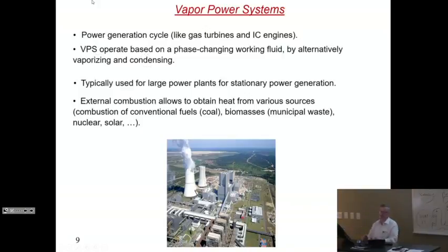That is quite important, because if you look at your thermodynamic tables, at your steam tables, going from a liquid to a vapor implies a very high change in entropy, in enthalpy or in internal energy, much more so than heating up a gas or heating up a fluid. Going from fluid to gas takes a lot of energy. So it takes a lot of energy and it gives a lot of energy, which means that these things are actually quite compact. They have a lot of power per kilogram of material that we're going to pass through these cycles.